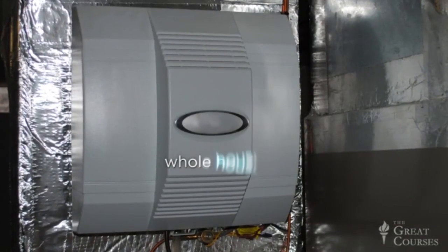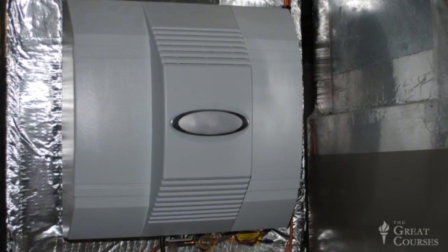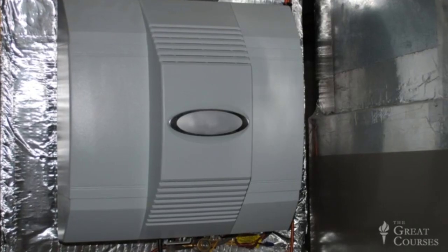Another common complaint about forced air systems is that they produce excessively dry interior air, leading to dry skin, sore throats, greater susceptibility to respiratory ailments, and excessive shrinkage of wooden floors and trim. An effective remedy is to install a whole house humidifier, which attaches directly to your main supply plenum, like this, and adds moisture to the circulating air. But don't overdo it. As we discussed in the lecture on the building envelope, if your home's interior air is excessively moist, water can condense inside the wall cavities, leading to the growth of mold.